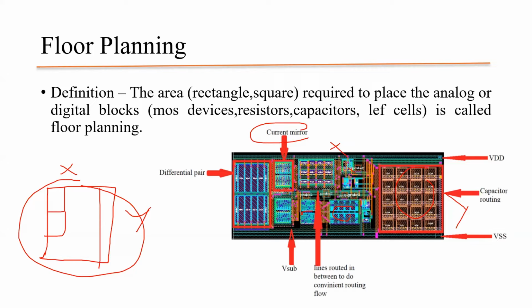LVS, and the delay of the signal should be minimal, because if we do long routings for the critical nets, the delay will of course increase. So we need to make it quality and optimized, so that there is no problem afterwards. Once the floor plan is done it is irreversible, and rework is quite time-consuming and not cost effective either.